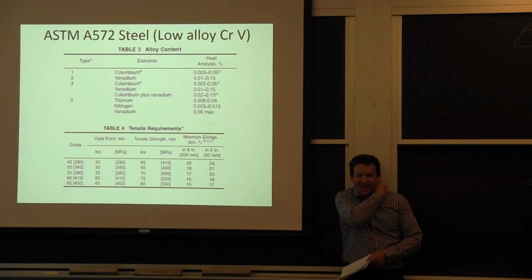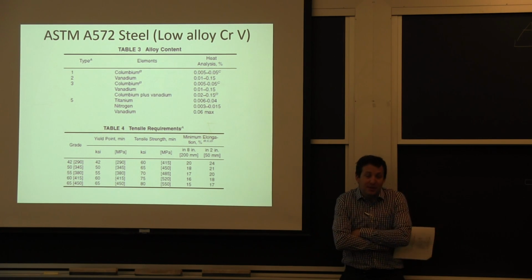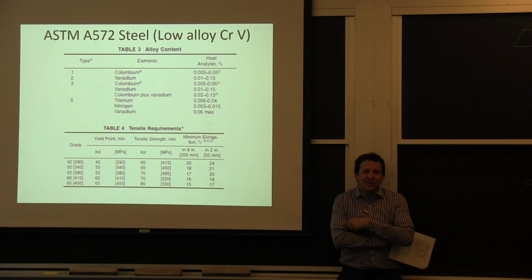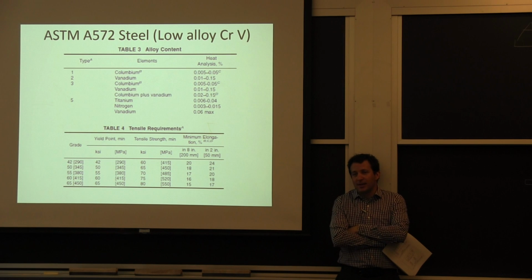Okay, tell me a little bit more about that steel. Well, it was put in here, we think, about 60 years ago. Oh, okay. So you have to go through that process of determining whether we are going to be able to weld this. The first thing I would always ask for is a chemical analysis, because otherwise it could be anything. It could be high-strength steel that you can't weld.